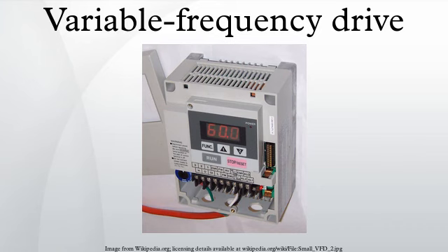A variable frequency drive is a type of adjustable speed drive used in electromechanical drive systems to control AC motor speed and torque by varying motor input frequency and voltage. VFDs are used in applications ranging from small appliances to the largest of mine mill drives and compressors.